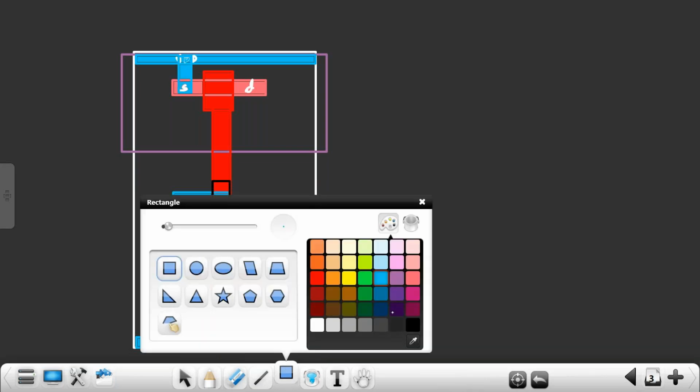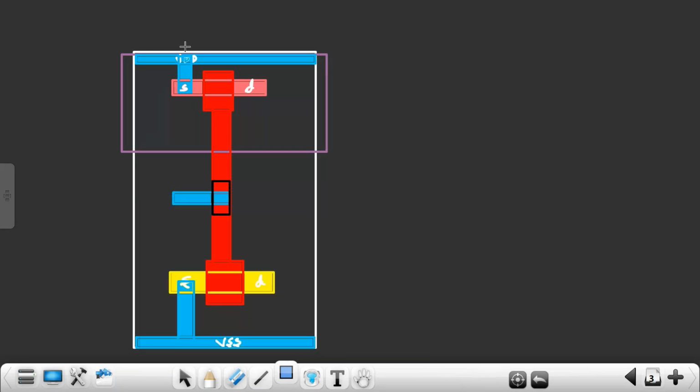And this is the contact cut. And this is a contact cut. Sorry, here I don't want it, right? Here I want one contact cut. Here I want one contact cut, because this source and drain is a semiconductor, N plus N type semiconductor. But this blue color is the metal layer. When a semiconductor is connecting to a metal layer, I want one contact cut. Here also I want one contact cut. So this connection is done.